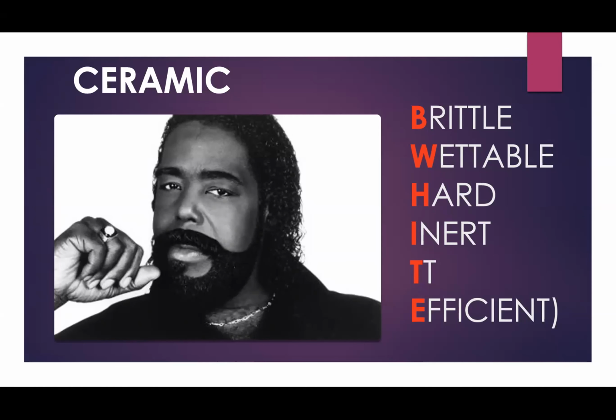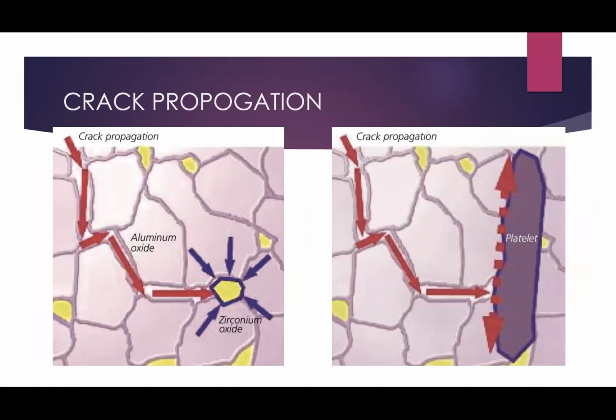Studies have suggested that squeak doesn't really affect the longevity or function of an implant, but it does appear to be a consequence of disruption of the fluid film lubrication, causing inadvertent metal transfer in a bearing. So anything which increases the metal debris, for example, third body wear, which I'll talk about later, can increase this disruption. I want to mention briefly about crack propagation.